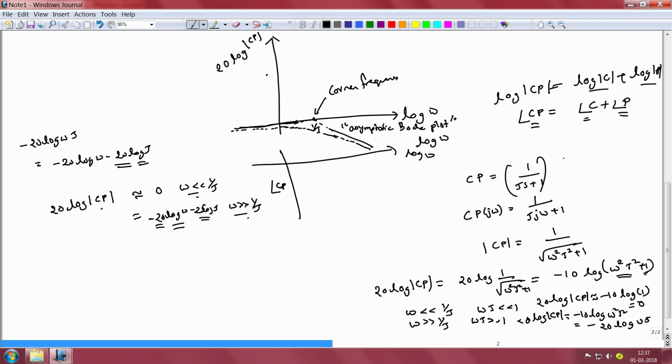So these are the three reasons why Bode plots are preferred over Nyquist plots. The first is that it converts a product to a sum, and therefore makes it more intuitive to anticipate the effect of having a controller transfer function on top of the plant transfer function on the overall stability of the closed loop system. The second is that the Nyquist curve of C times P is not intuitive, whereas the curves are now transformed to a set of broken straight lines, where the slope of the straight lines changes at the corner frequencies of the plant or the controller.